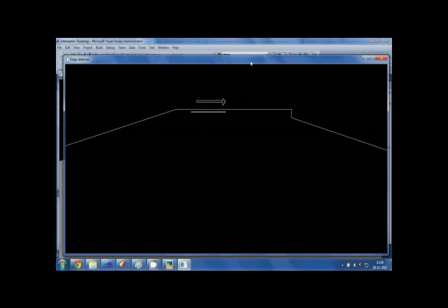Now how would one analyze something like this? Well, for starters, we wouldn't want the upper part of the image to disturb us just yet. At the end of the corridor, of course, we will need to recognize the arrow, but right now we just want to focus on the lane. So what you could do is, again, assuming you've gone through the image processing tutorials and you know how IP works, you can choose to exclude a certain portion of the top of the image, and focus only on the bottom portion of the image. You could do something like that. And now what will you do with that?